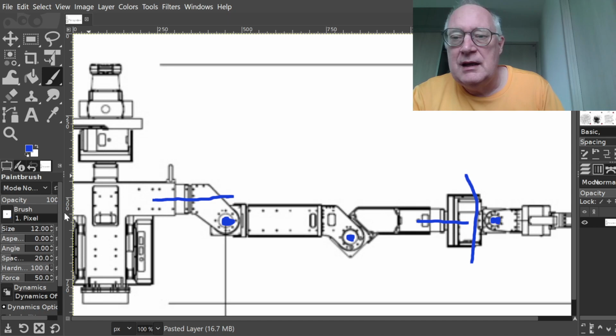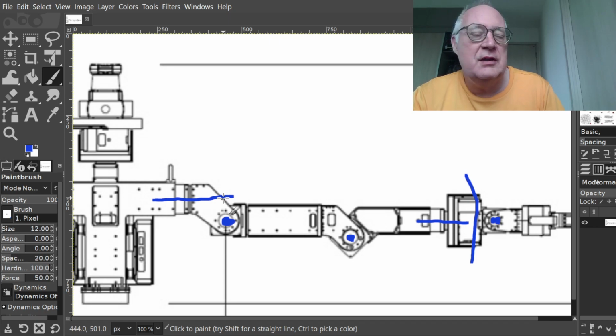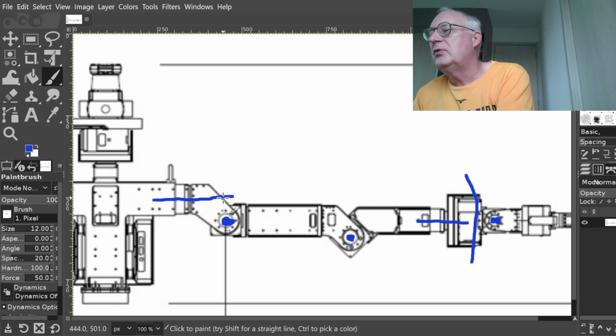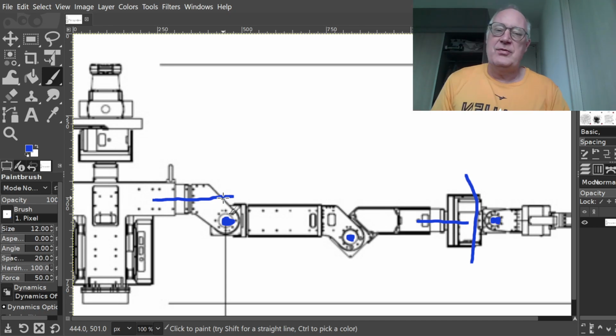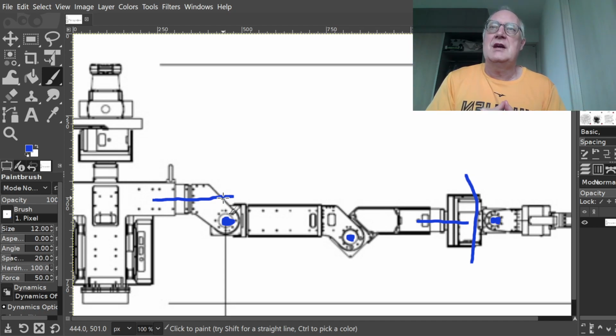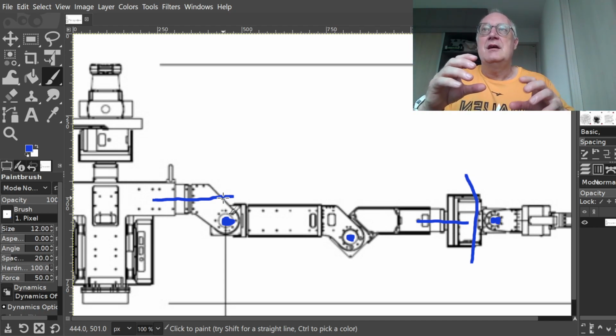So I like to assign the z coordinate in such a way that matches, because otherwise it's a little bit confusing if in your kinematics you move by -5 degrees and then you look at the servo joint rotating and it actually rotates in the other direction.